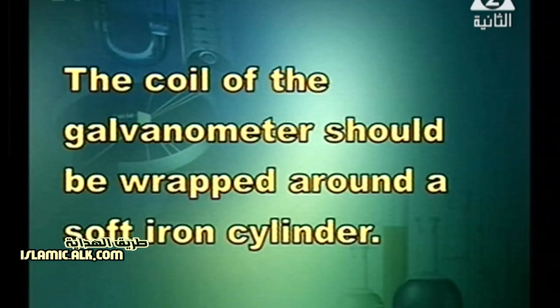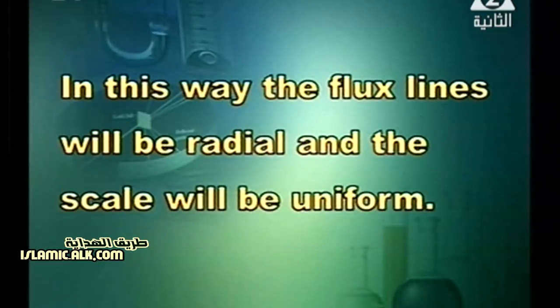The coil of the galvanometer should be wrapped around a soft iron cylinder, a soft iron core, to produce radial magnetic flux. In this way, the flux lines will be radial and the scale will be uniform.